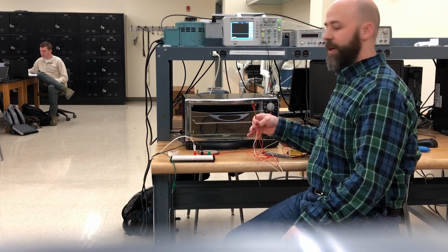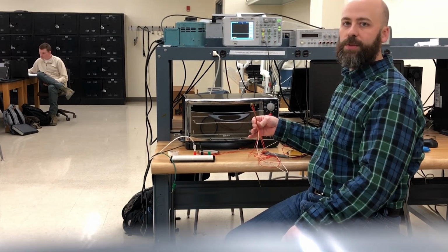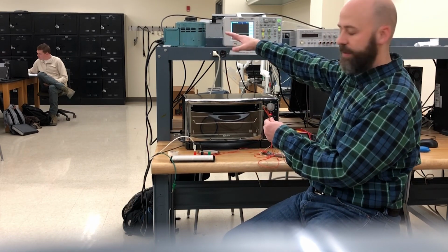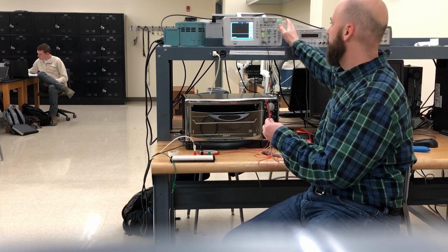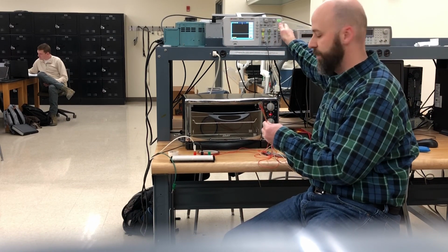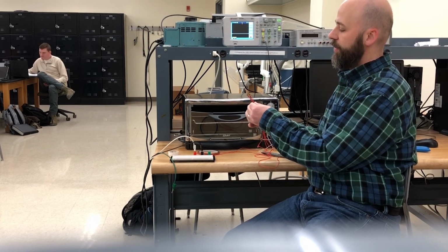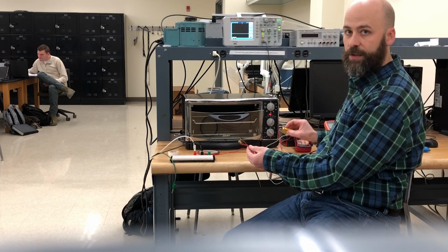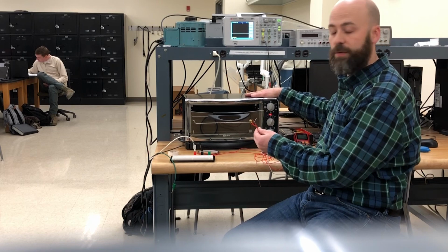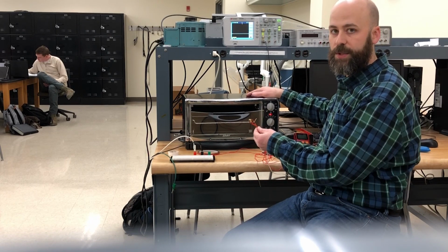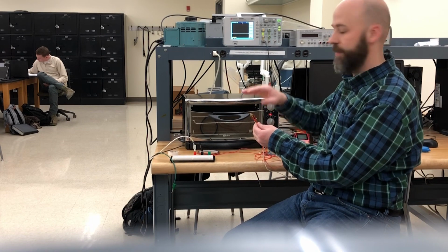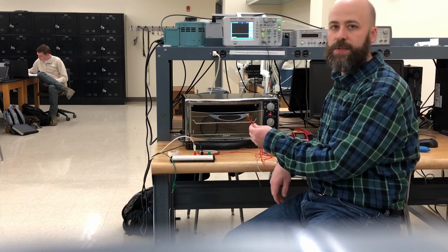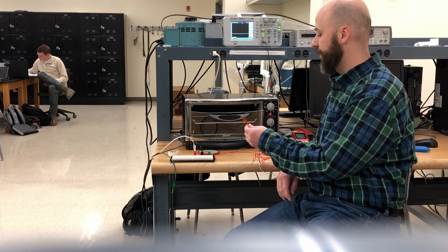Hey everybody, this is going to be our process and procedure for testing the thermal threshold of an IC rectifier chip. What we have here is a variac set to a certain AC voltage. We're going to use an oscilloscope to measure that voltage and view the waveform. We have our IC hooked up with a thermal probe attached to the top using thermal tape, and a load resistor external to the oven itself, so it's not impacted by the high temperatures. We're only looking at the high temperature effect of the rectifier itself. And we're going to take temperature, current, and voltage measurements as the temperature is increased during the test.